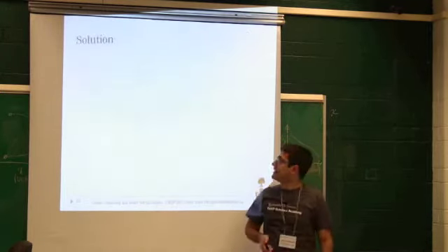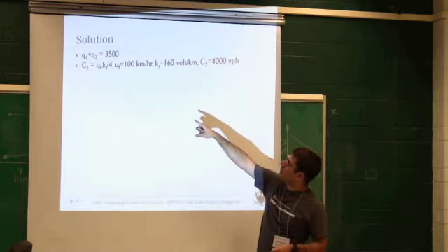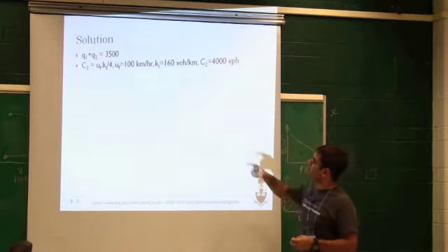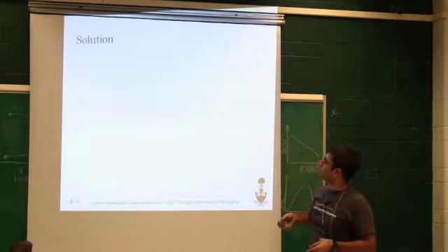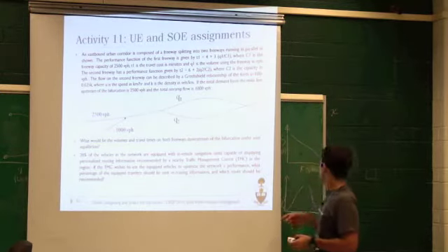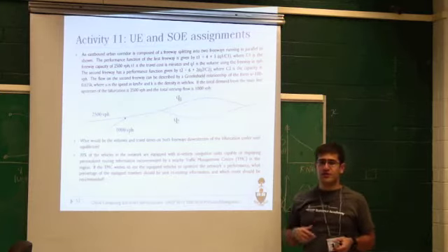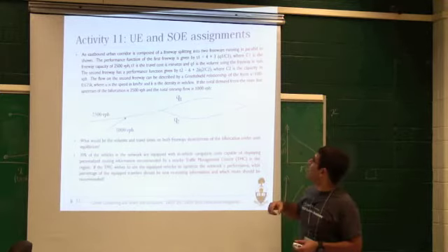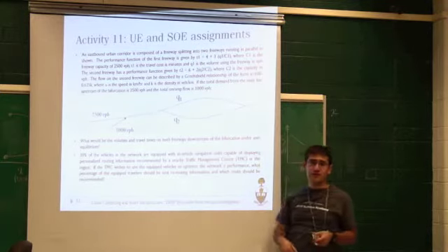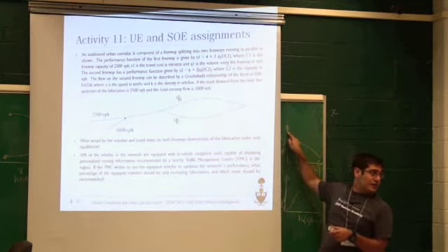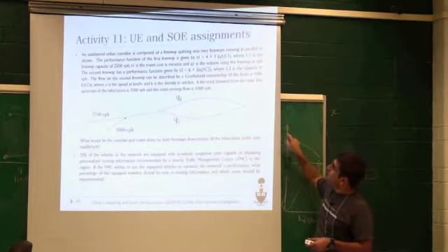The other thing is C2, or Qmax of link 2, has that formula of Uf times Kj, or rho j, over 4, which is what we covered earlier. If we put this formula, U is equal to 100 minus 0.625 K, on top of the formula that we had earlier, which is Vs is equal to Vf minus Vf over Kj times rho, we find out that 100 is actually the free flow speed. When density is very, very low, 100 is the free flow speed here.